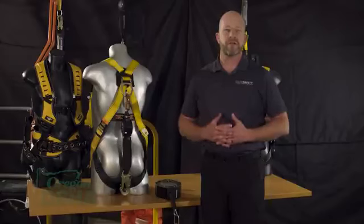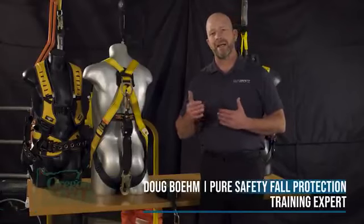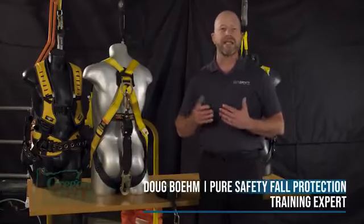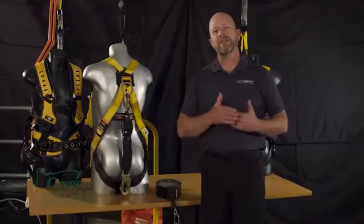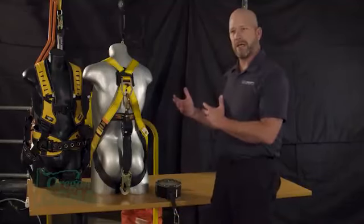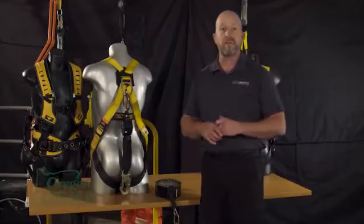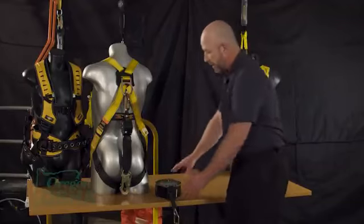Another version of SRL that you're hearing commonly in the market is that of an SRL LE. LE stands for leading edge. Now that's a specifically designed piece of equipment because, again, same thing as with the lanyard connecting devices, we don't always have an anchorage that is here or above. And in that case, using a retractable with foot level tie-off being worst case scenario,